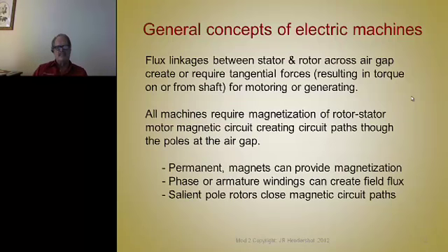It's really quite amazing that you can get so much force created in air, and it's the magnetic field that's created by either electromagnets or permanent magnets that creates that stress. I think if you look at the air gap stress in electrical machines, we're going to study that later, but the highest ones that I've ever seen put out 35 pounds per square inch of air gap stress.